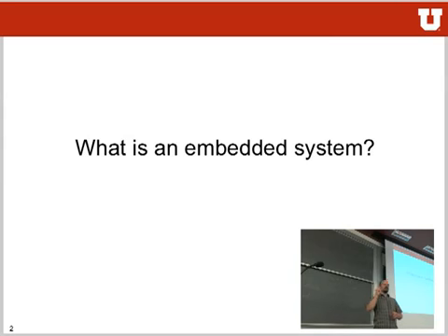If it's just a really dumb little RFID chip, like the ones that you have on clothing these days, they are not embedded systems. All they have in them is a little bit of logic that just replies an ID back. But there are smarter RFID tags out there, especially active RFID tags. They have logic and smartness in them, they actually do calculation and math inside of them, so that they can do a lot more than just telling you a little ID. For example, some of them have flash memory in them that you can write into with your RFID cards, and you can read that back out again.